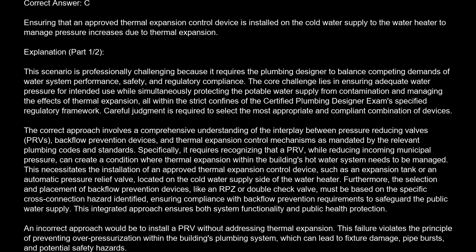Furthermore, the selection and placement of backflow prevention devices, like an RPZ or double check valve, must be based on the specific cross-connection hazard identified, ensuring compliance with backflow prevention requirements to safeguard the public water supply. This integrated approach ensures both system functionality and public health protection.